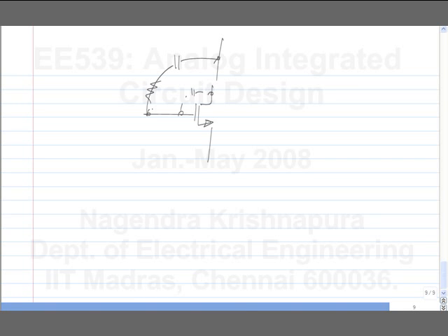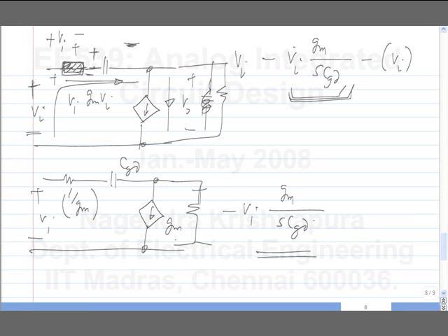Okay, so actually I should probably change my terminology. This does not refer to the intrinsic CGD. If you could put a resistor in series with that, that also works. Mathematically the technique works, but in reality you can't do anything to the intrinsic capacitance, or that's the meaning of the intrinsic capacitance. Okay. So if you have placed an additional capacitance for whatever reason, then you will get a zero. And as you increase the capacitance, the zero will move to lower frequencies. But you can get rid of the effect by adding a series resistor. Okay. So one thing you can do over the weekend is perhaps you add a load resistance or a source resistance and find the full transfer function and then see whether the result makes sense or not.